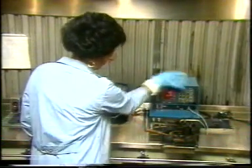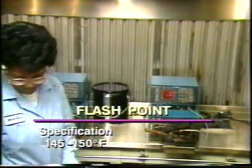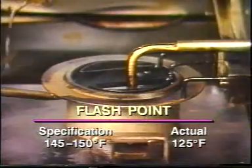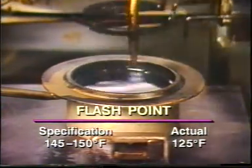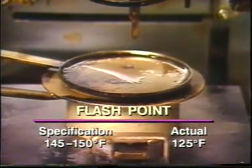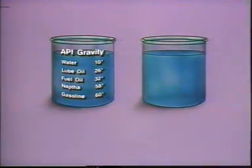Specifications on this product call for a flash point between 145 and 150 degrees Fahrenheit. The actual flash point is 125 degrees. This product is off specification because it contains too much light material. Many products must meet certain weight specifications. The lightness or heaviness of petroleum products is usually measured by comparing their weight to the weight of an equal volume of water. Two different scales are used to do this. The API gravity scale uses a reference in which 10 degrees API gravity is the same weight as water.